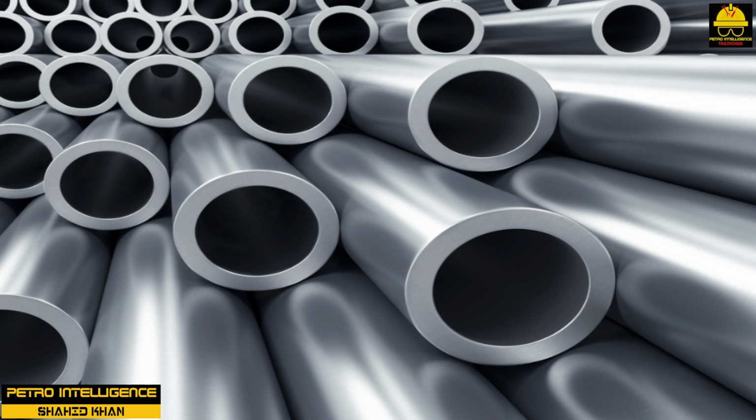At these temperatures, the strength of low-carbon steel is about 1/3 and 1/6, respectively, of its room temperature strength. As a result, the strength of this type of steel becomes so low that it is not a satisfactory material.